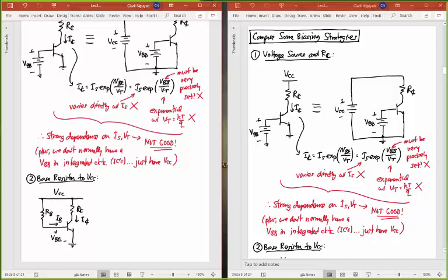Okay? And so with this, I can just do some very simple circuit analysis here. I could say that IB, I know what that current's going to be because I know that this VBE is going to be a VBE on across the transistor base to emitter. So I could just say IB is going to be VCC minus that VBE on voltage divided by that RB resistor.